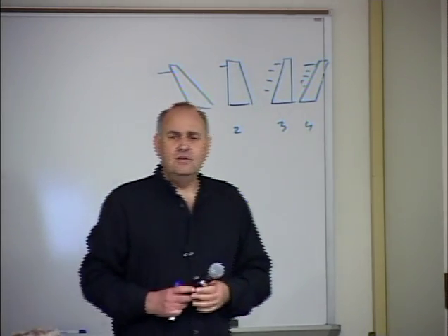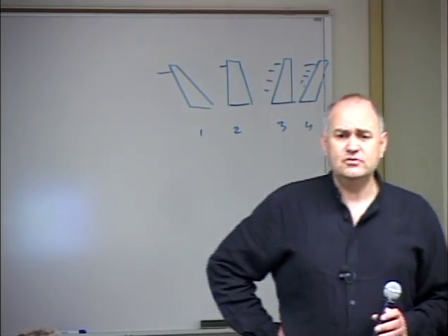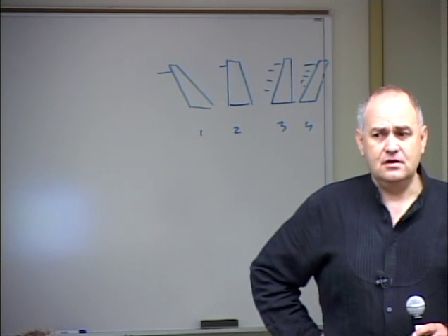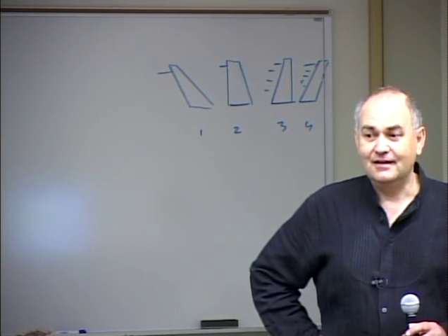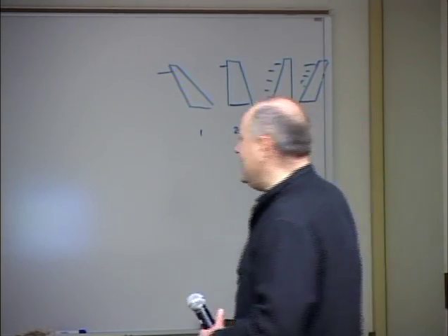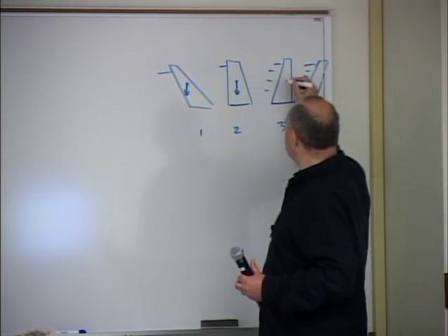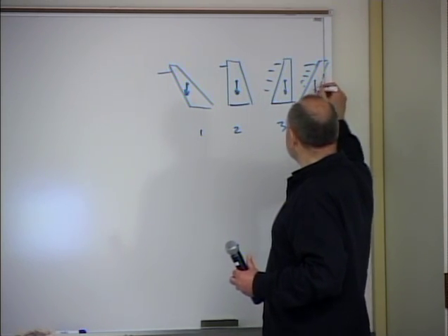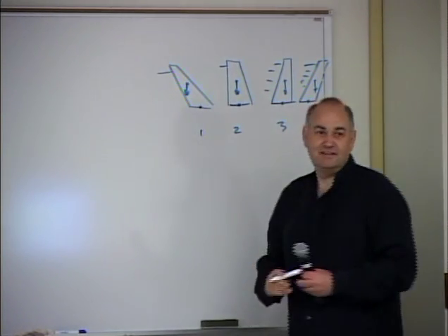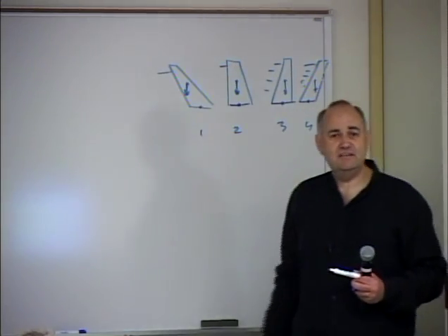However, if the water level drops, then it seems, why actually? I don't see exactly why the internal torque would have to reverse. Why doesn't it drop to 0 and the dam is relaxed? Aha, because we have gravity over here, right? Do not forget about gravity. Everywhere, our center of gravity is somewhere there. So now think about which way the gravitational torque is exerted. Over here, gravitational torque is exerted in the opposite direction than the torque exerted by water.